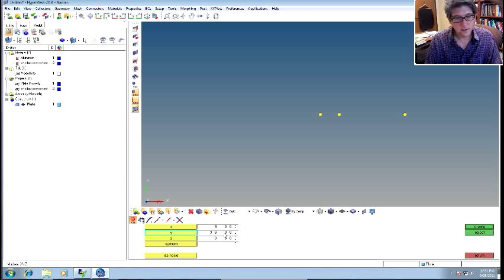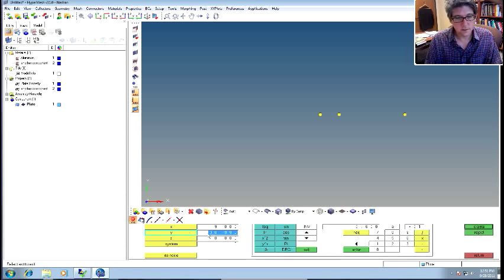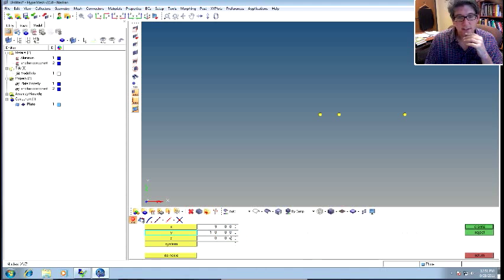It didn't do it. There used to be a way to do a calculator on this. I don't know how to do it. Oh, there it is. If I right click on it, you can see now I get a little calculator pops up. I can do 36, enter 2 divide, so that gives me 18, and then I can enter that in, exit. You can see it changes to 18. So you can use that little calculator if you right click on the field to do some calculations if you want. Okay, so now I've got 9 and 18.